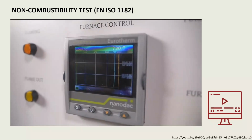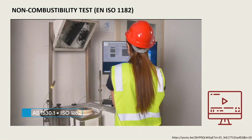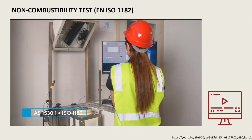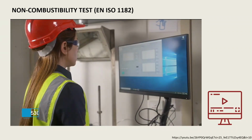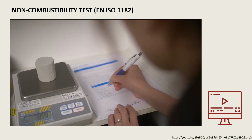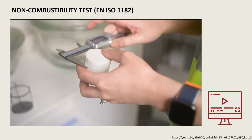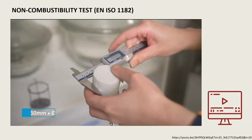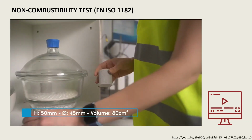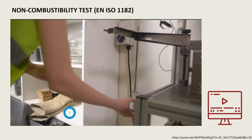In this video, we look at the test standard AS 1530 Part 1 and ISO 1182, which is used to determine the combustibility of a material based on its reaction to fire. The specimen must be a homogeneous material, nominally 50 mm in height, 45 mm in diameter and 80 cm cubed in volume. A 2 mm hole is drilled from the top of the specimen to the centre of the specimen